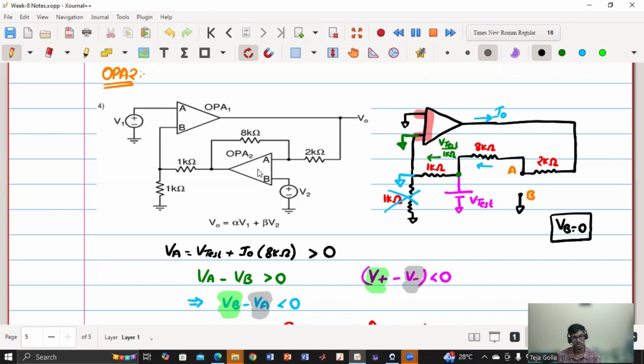But for the time being, you can think that negative feedback systems are stable and output will be some gain. As we are using this as an amplifier, it should be connected in the negative feedback. Then for stable operation, output will be a multiplying factor k times the input voltage. If it is connected in the positive feedback, either the output will be saturated to positive VDD or it will be saturated to negative VDD.